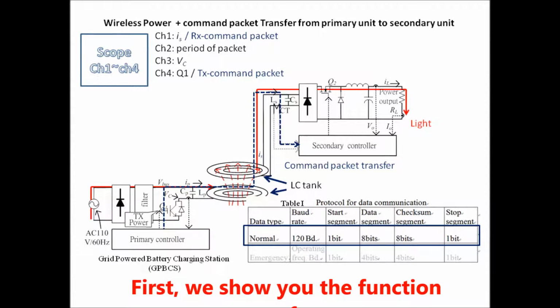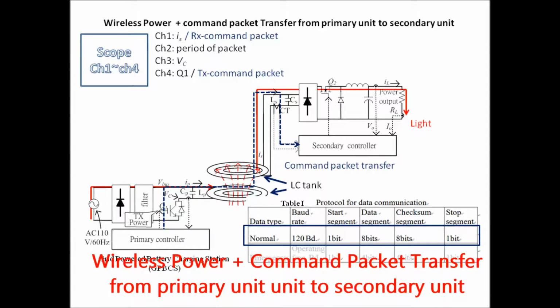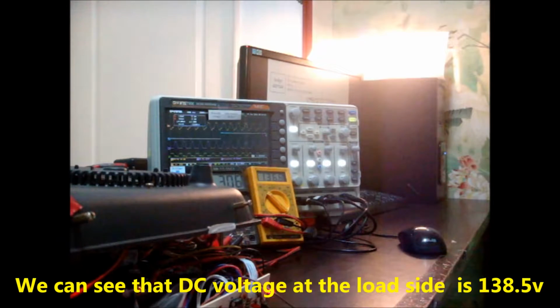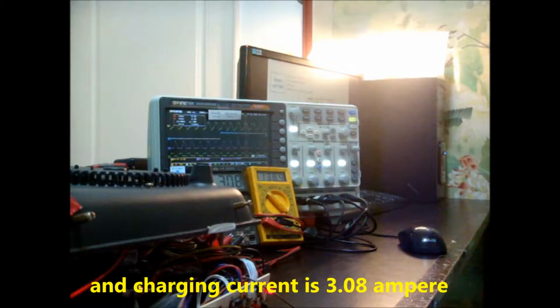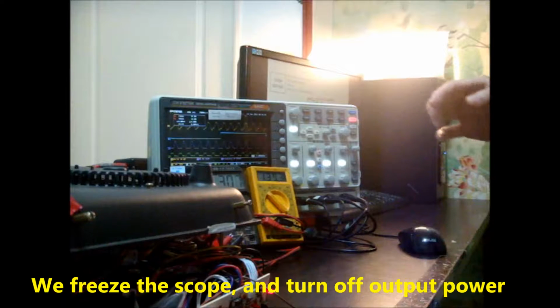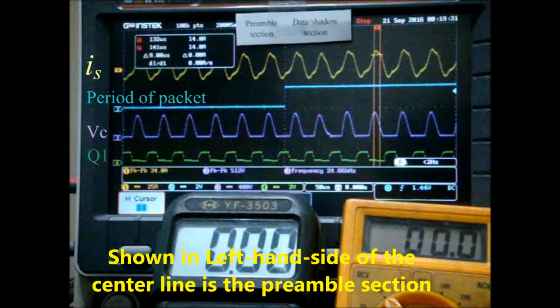Let's start the experiment. First, we show you the function of wireless power plus command packet transfer from the primary unit to the secondary unit. Let's start power transfer. We can see that the DC voltage at the load side is 140.5 volts and the charging current is 3.08 amperes. We freeze the scope and turn off the output power.